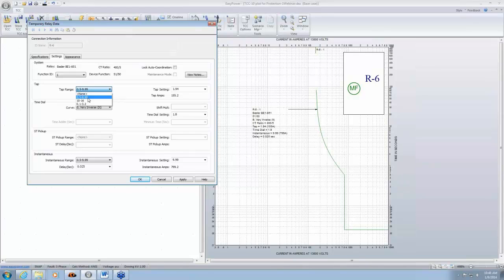What we've done is bundle up this information, just for the purpose of organizing and keeping it simple, and put the different ranges for relays in the same dialog. So choose the range, then choose the pickup, and choose what type of curve you have. For old-fashioned induction disc relays, it might be just one type of curve shape.